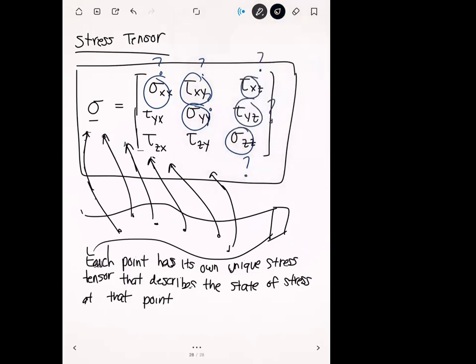The answer to that question is we're kind of seeing all of them at the same time. If you remember, when we defined our results for this activity, we defined a very specific name for the stress. We didn't call it a normal stress or a shear stress. What we said is we're viewing what's called the equivalent stress. Another name for this is the von Mises stress.